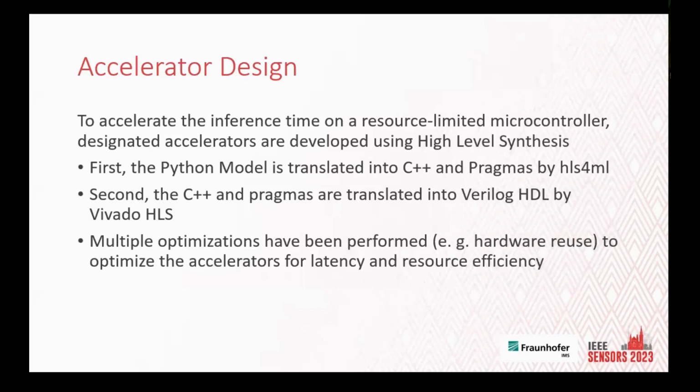Vivado, probably you know that, is a tool from Xilinx, which is specific for Xilinx FPGAs, which I talk about later in my conclusions. We've performed multiple optimizations to make it more efficient. Particularly, we've worked a lot with the hardware we use, and optimized in two ways. Once for latency to get the result of our computation really fast, and also for resource efficiency to get it into hardware most efficiently and to use less of the logic parts of the FPGA.